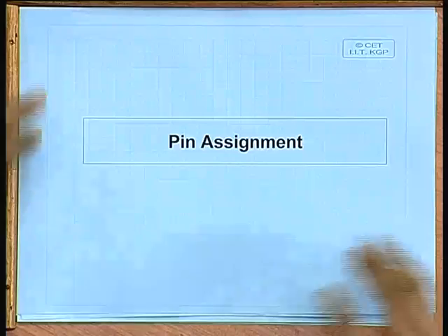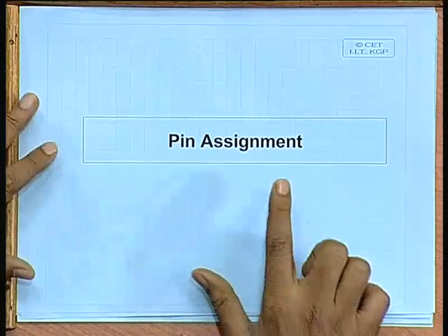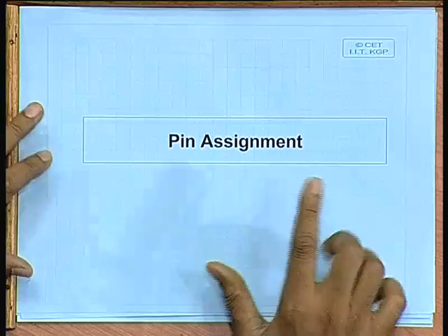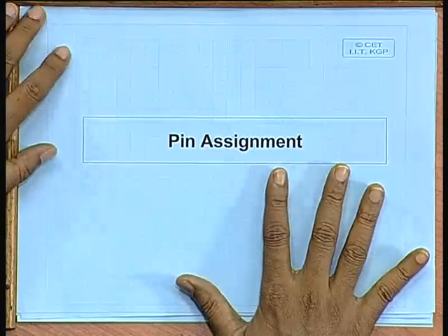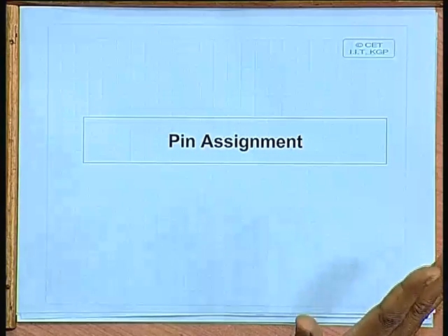Okay. So, we had looked at the different algorithms for floor planning. Now, there is another step to be done either during floor planning or immediately after that. This is called pin assignment. Apparently pin assignment is a much simpler subproblem as compared to floor planning, but we will see this is also important, because a good pin assignment can give you a very good layout finally. So, first let us try to understand what pin assignment means, what the problem is all about.